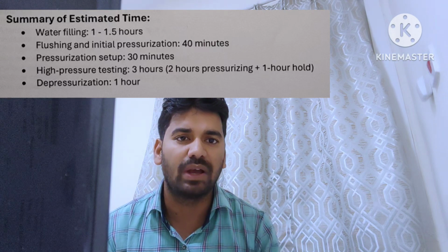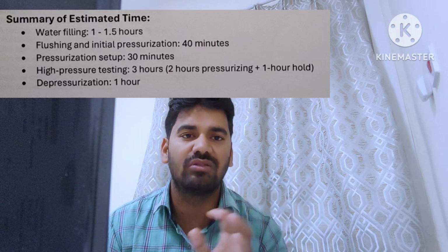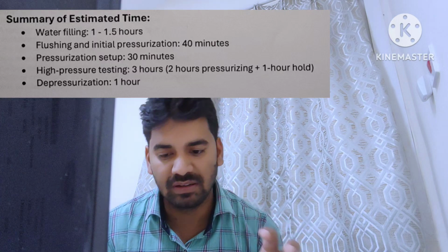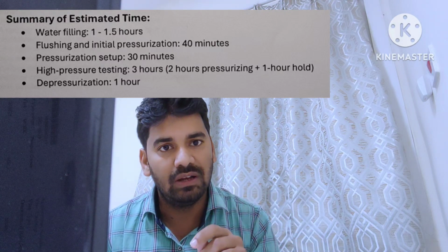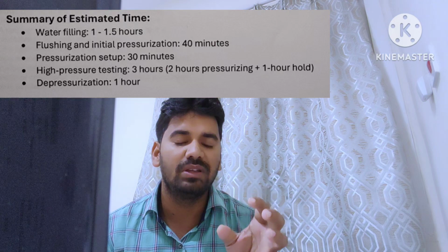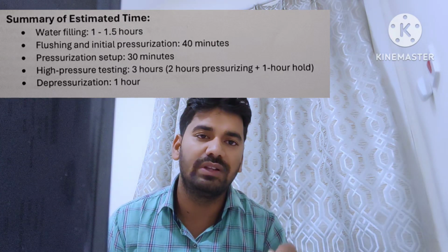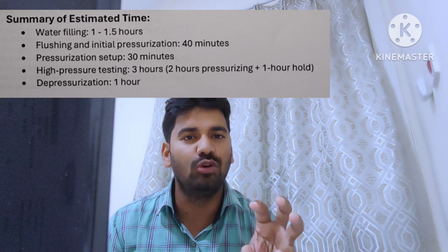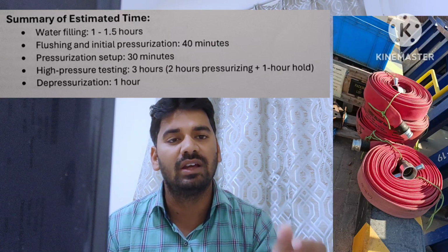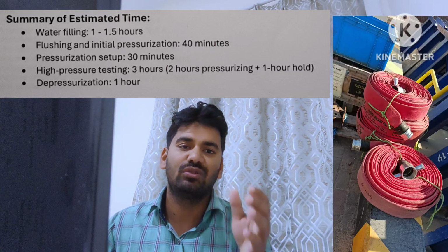The fire water hydrant capacity is 60 cubic meters per hour, as per my current job standard. That means in 1 hour it releases 60,000 liters, but my requirement is 37,000 or at most 38,000 liters for filling. So 37,000 liters would be filled within 40 minutes. But the problem is that when you open the fire hydrant valve, it is not fully open, only partially open, because he does not know whether your line has everything blinded or available.